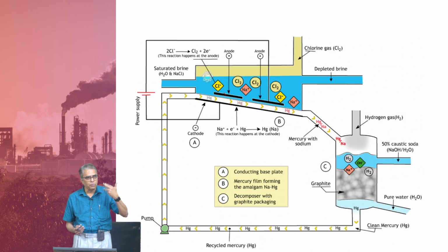So, the overall productivity of the production will come down. So, you must make it as thin, preferably a monolayer if you can escape from that, but if you make it too thin, so that there are pockets of mercury and pockets of water, then you have a problem on your hand, because that water will immediately react, like this situation will get repeated there.